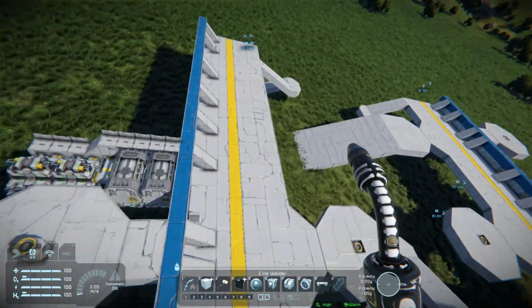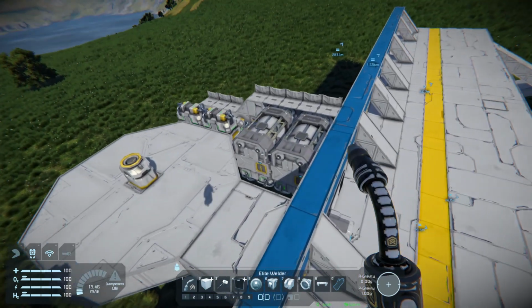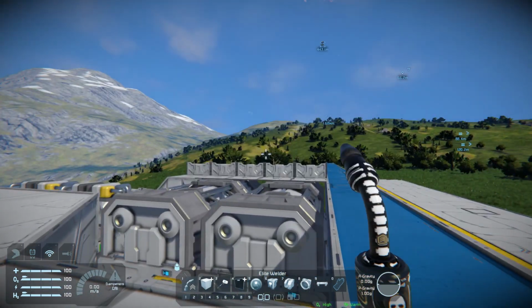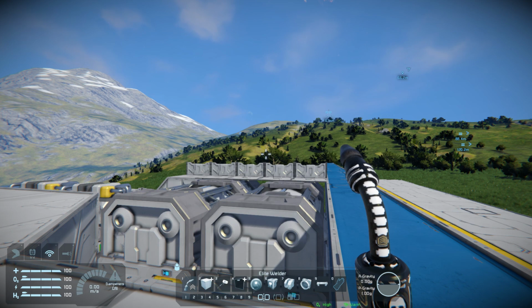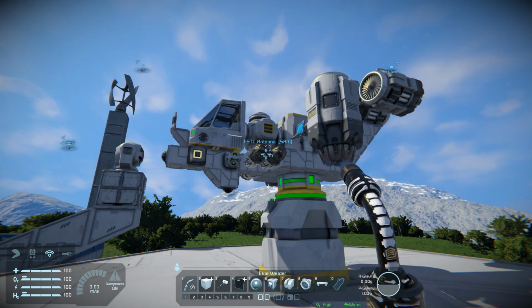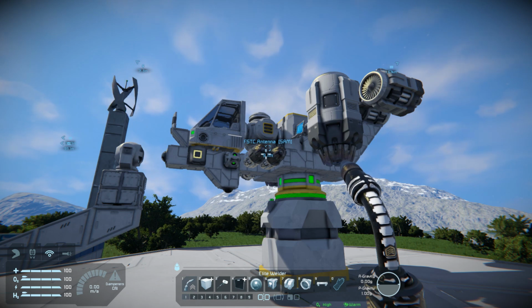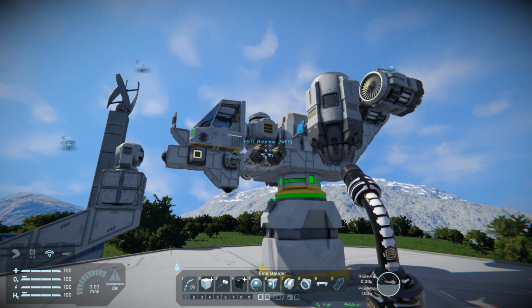This is pretty neat. You could set up a cargo drone that delivers cargo just by you pressing a button, for example. And this works with all the arguments. All the arguments just work also with buttons. As long as you can put it into the programmable block, everything works. Now you know how to set up the stations and the ships of SAM's Autopilot Manager version 2.